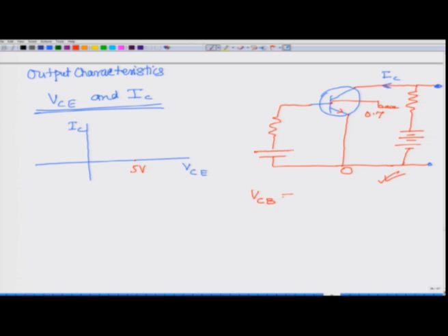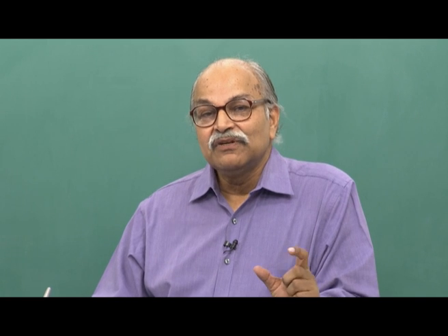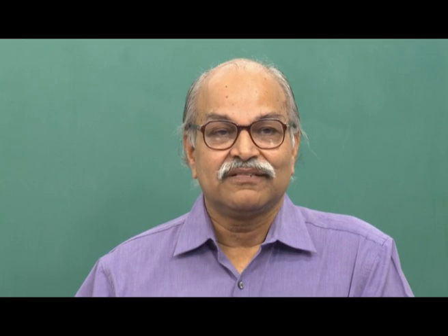This is the actual junction voltage. This will be your VCE minus that 0.7 volt, or you can write that as VCE minus VBE, and VBE is decided by the input circuit. So, if you put this VCE at 5 volts and if this VBE is 0.7 volt, then the reverse biasing voltage will be only 4.3 volt, but sufficient.